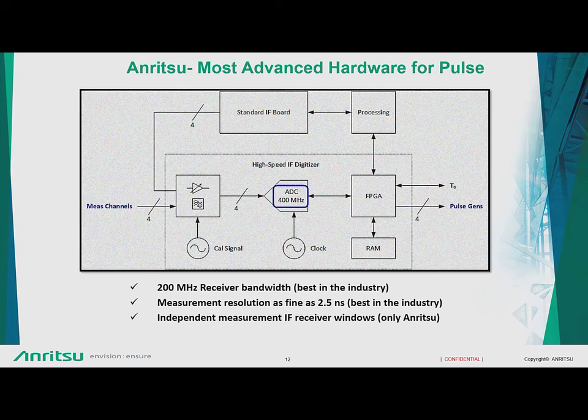Because, as I told you initially, if the device under test has some delays associated with it, and it has an input and an output port, and the transmit side pulse goes inside and takes a long time to reach port number 2, the two receivers are out of sync, and when they are out of sync, the S21 or the ratioed measurement can be affected. I'll show you how that is very important.